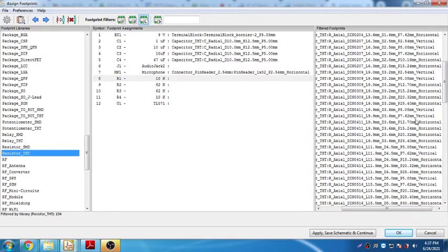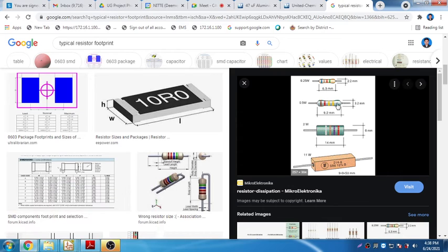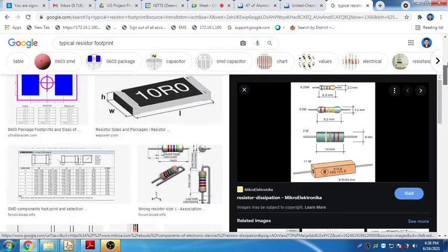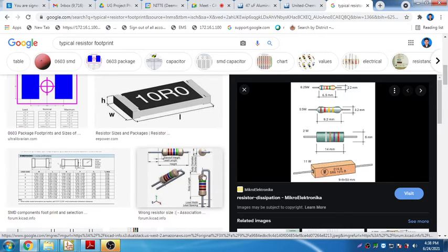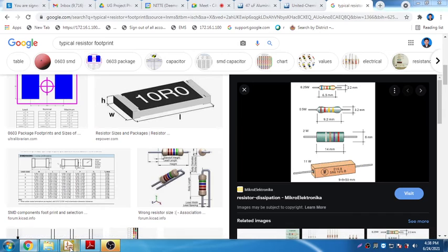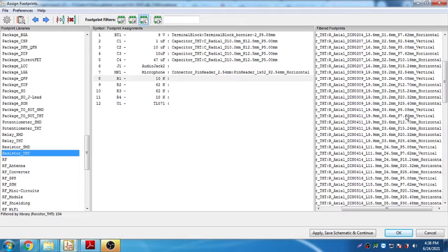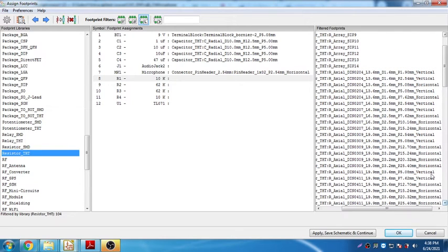Okay, and see, a resistor can be placed horizontal or vertical. Vertical in the sense that the placement of the component is made vertical. You might have seen a figure over here where a resistor, see, this is actually vertically placing the component. What you see here is the component placed vertically. Horizontally we place like this. So when you place vertically, the gap will be less. So that's what horizontal and vertical mean here. So we are somewhere at a pitch width of 6 point something over here.